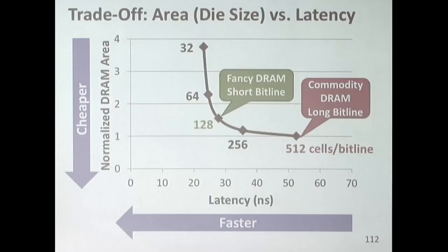But they're lower latency. These are actually used in specialized routers, for example. When you're bound by memory latency, you can buy that reduced latency DRAM. And I believe those routers are one of the major customers of this reduced latency DRAM. They're not manufactured at mass scale like commodity DRAM because they don't have many customers, and they're also expensive to begin with, right? And that's a chicken and egg problem, right? If you're expensive, you'll naturally have fewer customers, unless you market well.